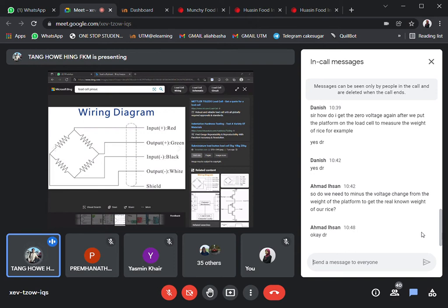So what is listed in the catalog is just for your reference. The main use of it is that you can compare with another system or another load cell to determine which load cell is more accurate. That's all. And later on, once you get that load cell, if you didn't follow their instructions for soldering and wiring connections, most probably you will not be able to get that accuracy as well.